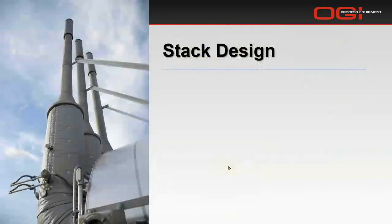And then finally, the last major assembly will be your stack design. You have people who use stainless steel, and then others who use carbon steel. With carbon steel stacks, they'll have to be painted, and although you're going to use a high temp paint, stacks can operate between 600 and 900 degrees, and in some cases even higher, depending again on your thermal efficiencies and if your burner is tuned. And so over time, that paint will peel and you'll have to repaint it. With a stainless steel stack, you don't have to worry about it. We feel that if you spend a little more money on a stainless steel stack, you'll save the headache later of having to paint it. Plus, for aesthetic reasons, it just looks nicer.